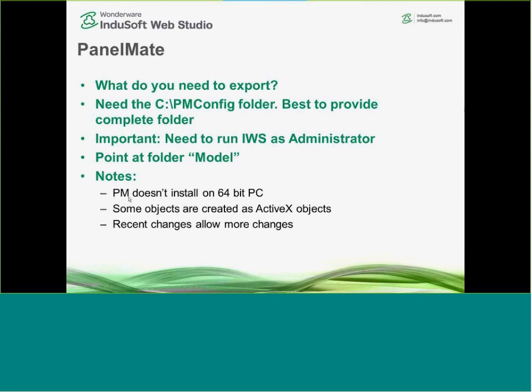Note that PanelMate software does not install on a 64-bit PC. So if you've got, for example, Windows 7 or Windows 10, and it's a 64-bit runtime, you're not going to be able to install the PanelMate software. But all hope is not lost, because you can go back to your, let's say it's a Windows XP machine or even previous, you can go back to that and zip up or copy the PM config folder and provide that, and we'll still be able to bring in those projects.